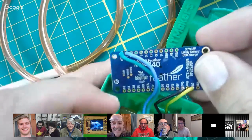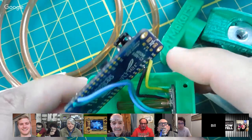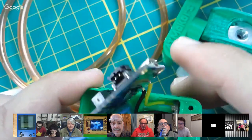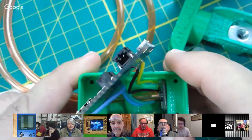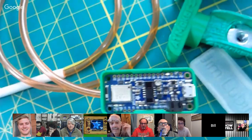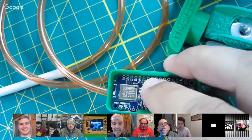So here's the 840, and you'll see in there, I did have to do something kind of funky in order to get this tube to stay on. I actually had to have it go through these 2 frictional rings. These are too small for it, so it actually holds it in place. I'm working on that. One thing to mention, if you're ever going to use this, is it needs a 2.5 millimeter internal diameter hose, and that is not standard. So it's possible to buy it, but it's not something you're going to find at your local Lowe's. So I might give you a request to update that guide. But once that was done, this will work great for him, and it works great.